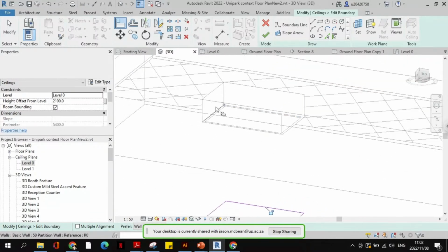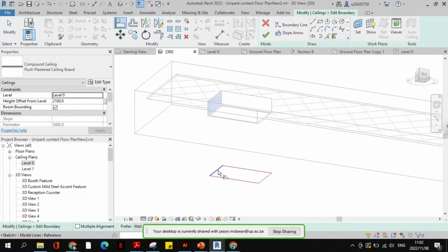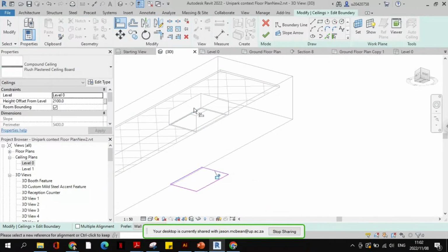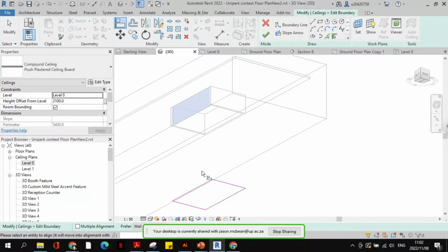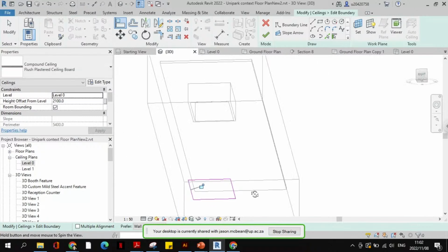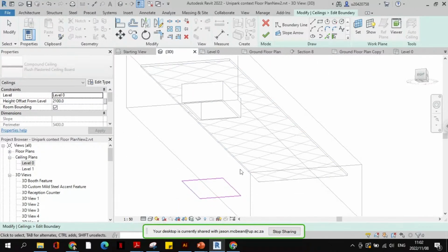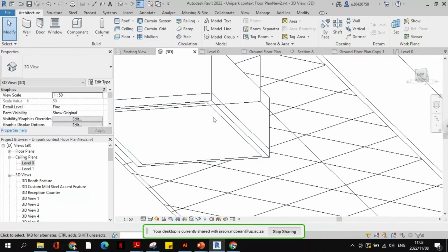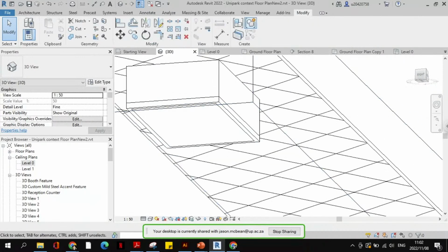You create a section, you create a 3D section through the building, and you can build these things quite rapidly. And if you start understanding where the levels are, you can do everything in ceiling plan view and that other plan view that you made. Now, if I do this and I join these things, what happens if I go to join now? So here, if I go to modify and I go to join, that with tab, so tab that. Now these things actually join together.